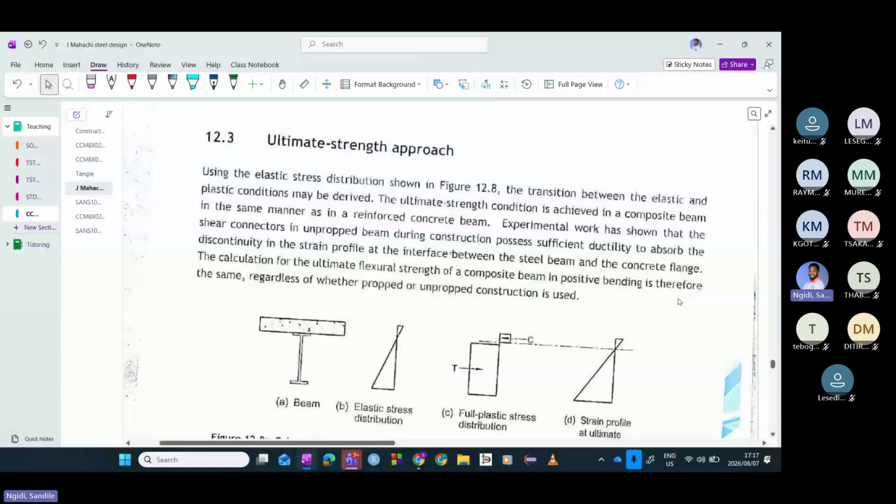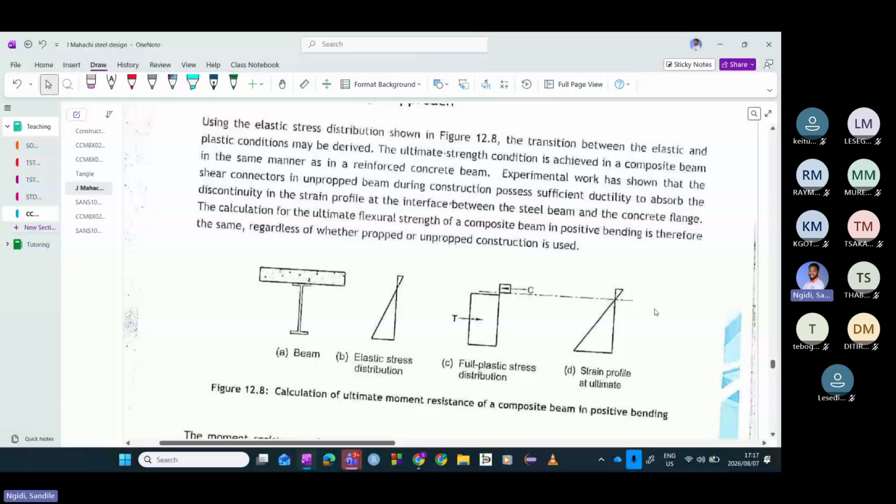Which means that if we have a beam that has steel at the bottom and concrete on top, then we can draw the stress distribution diagrams, and we know that there are forces being applied. There's a tensile force at the bottom of this section by steel, and there's a compression force at the top of this section by concrete. So we know that that is very important.